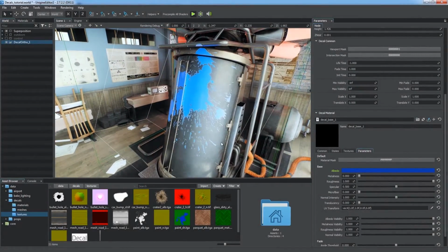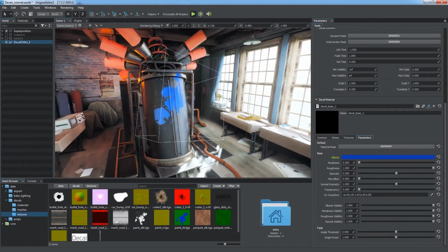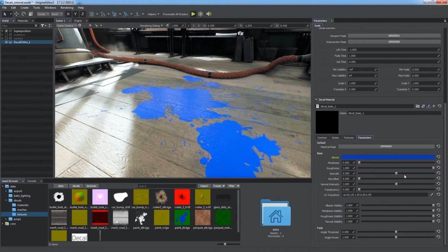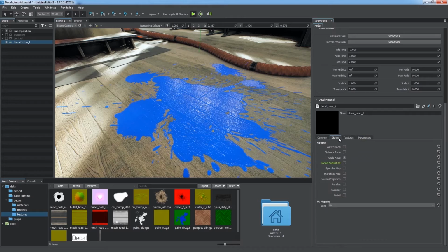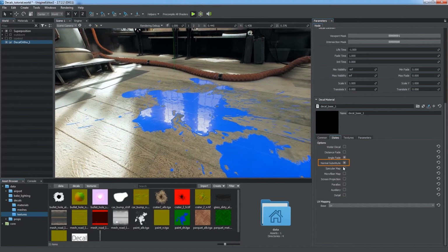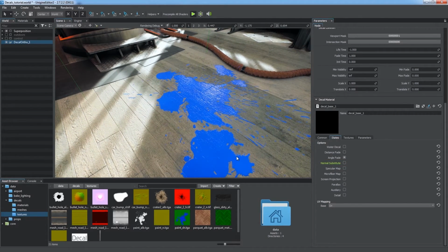You can control the intensity of shading components of the decal individually via the visibility parameters to achieve the desired result. Different results can be achieved by changing the way the normals are treated. You can see the original floor relief under the splash that looks dry at the moment, but enable the normal substitute state and the paint layer will become thicker as if it had just been poured. The state defines whether the decal normals overlap the normal map of the ground.